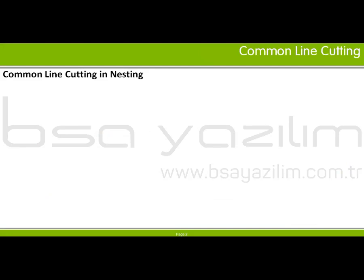This month's video looks at the options and settings for Radan's common line cutting feature. Common line cutting is the process of cutting two different part edges simultaneously with one cut.